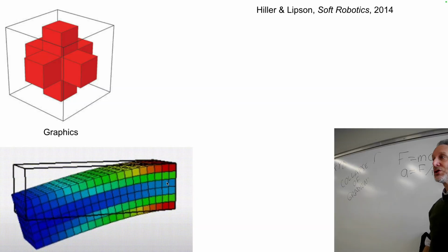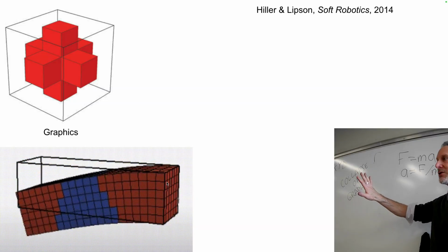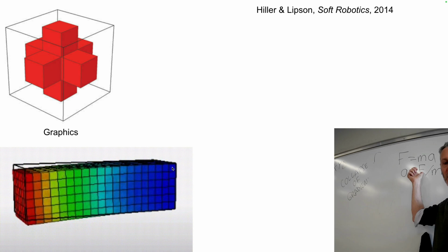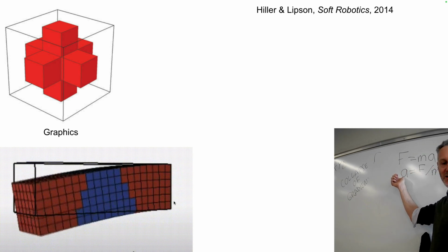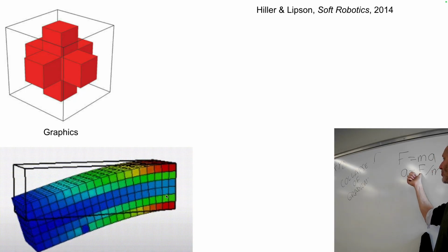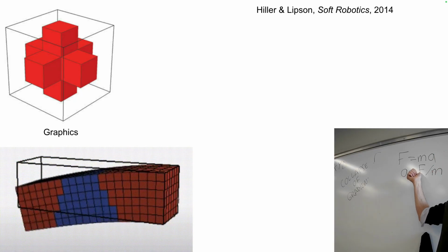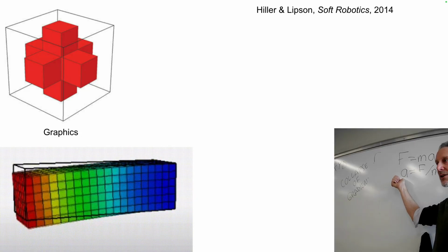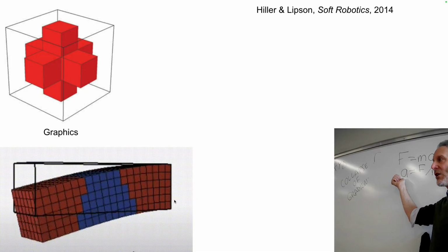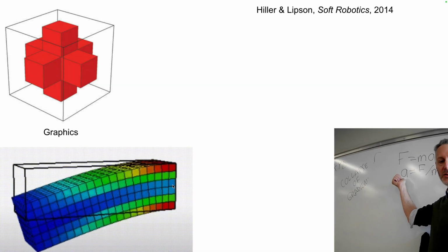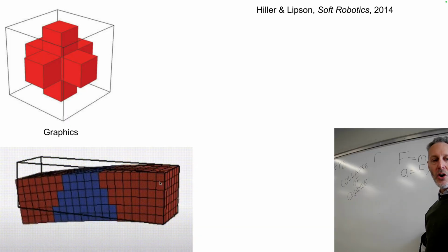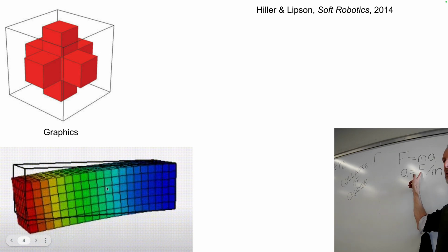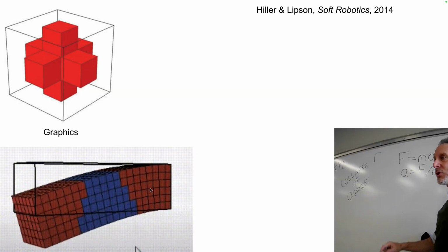It's glued to the wall, which you can think of as contacts. We talked about contact detection and resolution in the lecture on physics engines. That glue is applying a counteracting force to just these voxels here, which alters the acceleration of these voxels. In essence, the glue cancels out the downward force, which means for these voxels at every time step, the net force acting on them is 0, which means their acceleration is 0, which means at the next time step, these voxels don't move. These voxels are attached to these voxels, which in turn alter how these voxels move. So these voxels are not just being acted on by the downward force of gravity. These voxels are applying a force to these voxels.